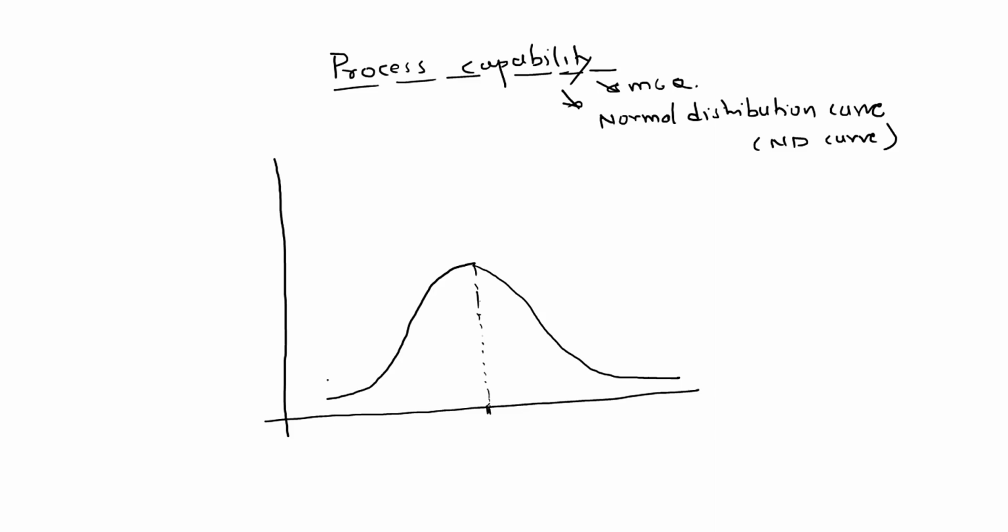This is the mean of it. This axis is called the size deviation, or any deviation you can say. If you are discussing it in mechanical, we generally have the word size deviation because we measure something in metrology. This axis is frequency. That means the frequency of occurrence of that size will be shown on this axis, and this is generally called the basic size or a mean about which the data will vary.